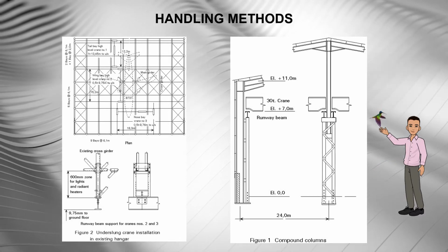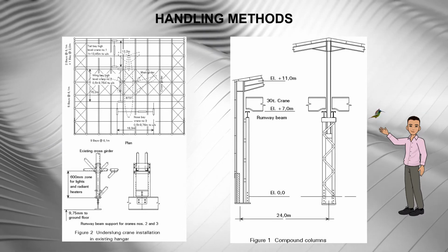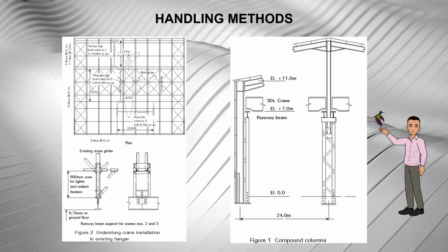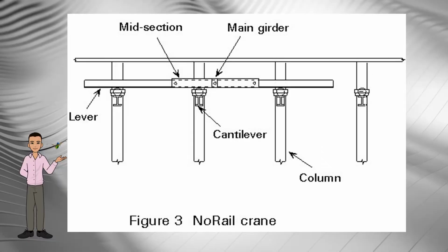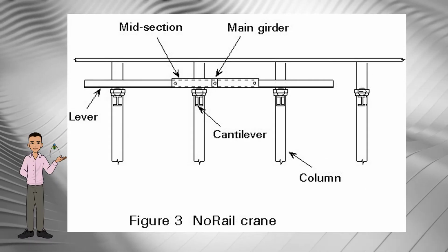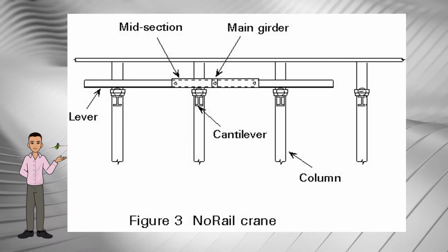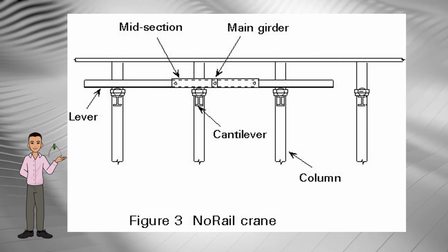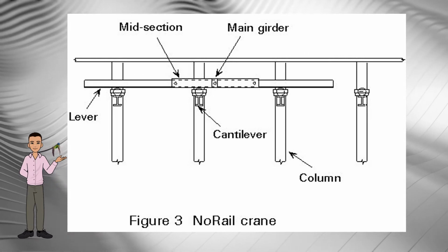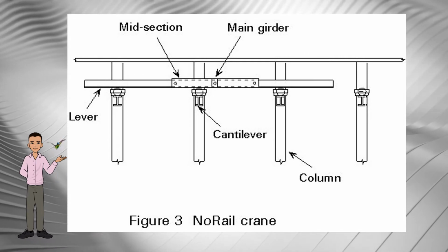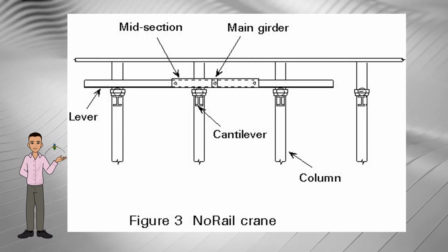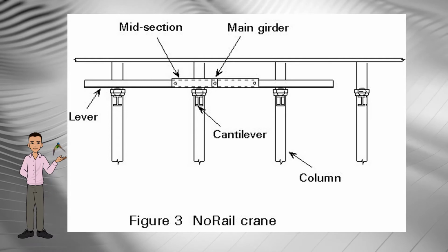Roof flexibility may become important too for roof-mounted cranes used for assembly. Some years ago, so-called no-rail cranes were developed. The no-rail crane concept inverts the overhead crane principle. Short rails are mounted in the end truck of the crane.